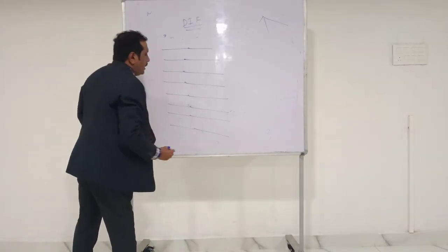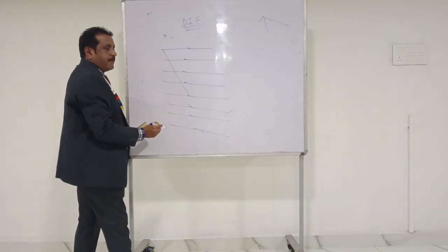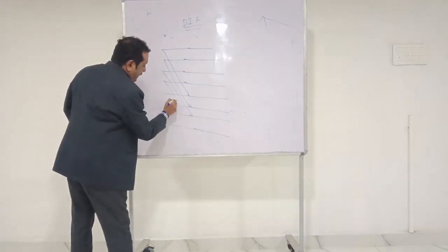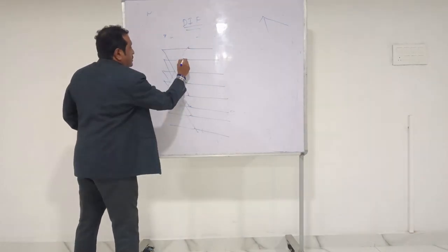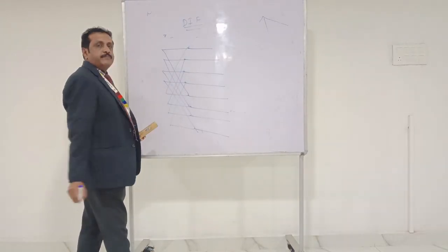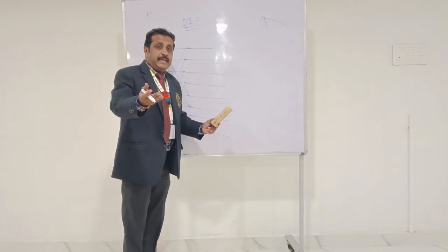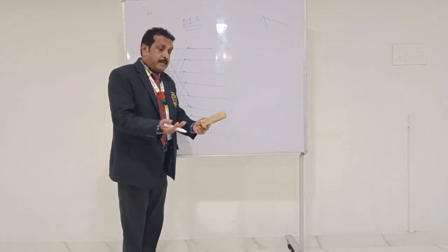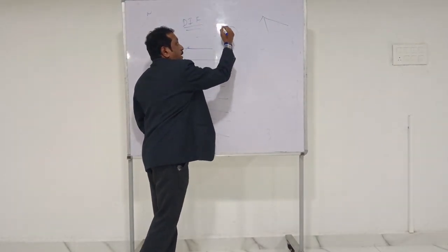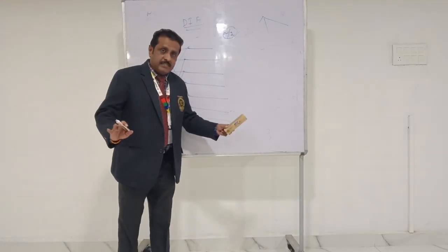8 lines. And you can connect the lines like this based on the basic graph. First to 5th and 6th, 7th and 8th, and the reverse process also. You can connect, you will make the butterflies here. The butterflies will be at the first stage in DIT. But even in DIT, the number of butterflies is the same. The total number of butterflies in each stage is n by 2 in both the DIT and DIF algorithm. That will not be changed.